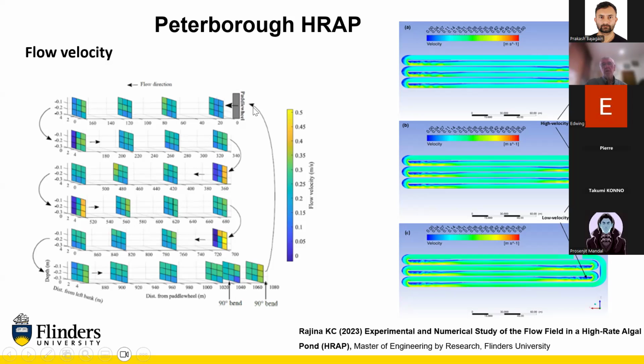And what we've got here are the flow velocities measured in meters per second. So here, when you've got a dark blue, you have virtually no flow, whereas here, you've got a flow of 0.5 meters per second, the liquid flow velocity. And what you see is it's really quite homogeneous. You're talking about 0.3 to about 0.5, some lower ones.